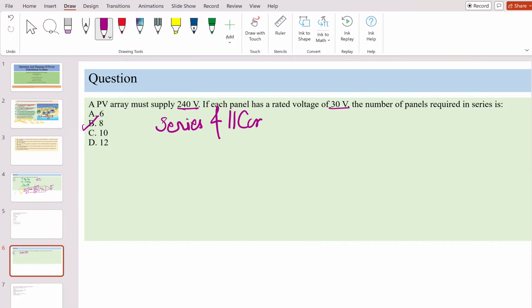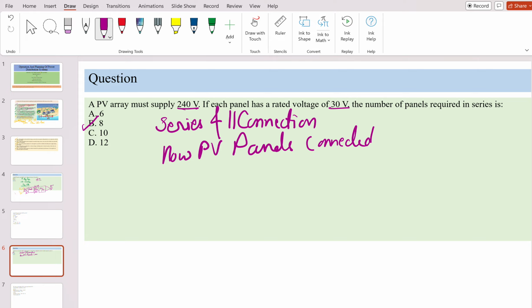Okay, so how the panels get connected, how the PV panels actually get connected. Suppose for the generation, this is one DC PV panel, so it will have two points, one is the positive, one is the negative. Suppose I wanted to make a string out of that. So through this negative you will connect another PV panel. Okay, PV module, basically this is the module we call.